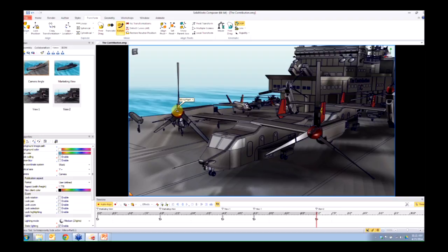it will look fine like this. As soon as the plane starts flying forward, those parts will stay where they're at, and the propellers will still be spinning here while the plane's in the air somewhere. And there'll be this disconnection between the parts, and it'll be very difficult to ever get correct. So trust me, it's how I learned. It was very frustrating until I figured out, hey, if I use assembly selection mode, I can get around this, and it's a nice little trick.